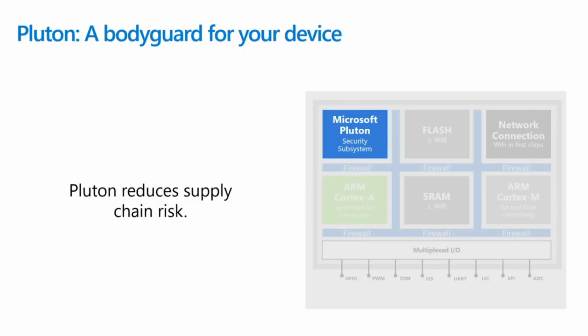It reduces supply chain risk. What do I mean by this? There's a great story you guys can look up out there of a certain model of phone that one of the warehouses was physically attacked, and they rooted 52 models of phone and put malware on it. So when these phones arrived at businesses, they came out of the box with the cameras on and the microphones recording. So having secure boot, guaranteeing that every piece of software is signed, eliminating the ability to have something like a rooted or development mode that someone can arbitrarily turn on, eliminates that type of risk.